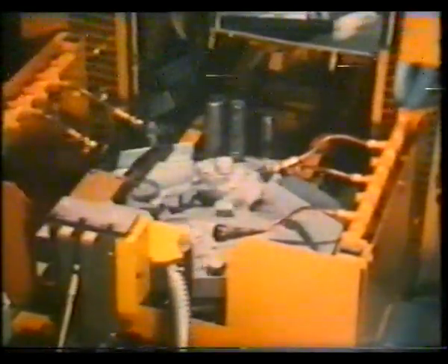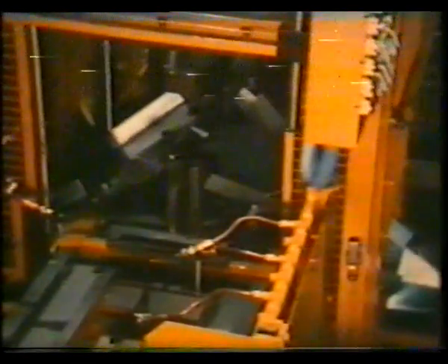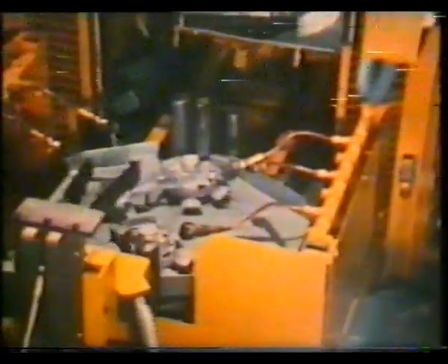The accurate positioning of the casting extracted by the pick mat unit allows the part to be placed direct on the sliding table in its correct position. The cooling station with its thermostatically regulated cooling circuit ensures uniform cooling and thus optimum trimming conditions. Besides cooling, the flexible spray nozzles also clean off metal chips from the trimming tool, ensuring trouble-free operation.